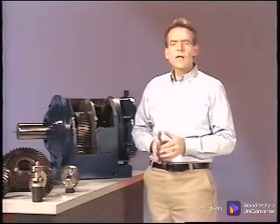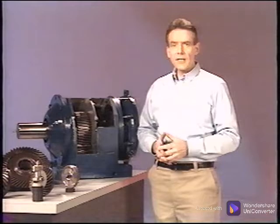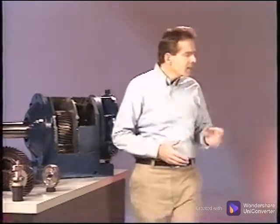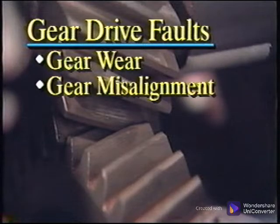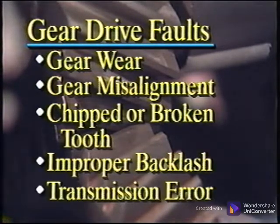In the previous section, we pointed out how gear mesh is generated and how it is directly related to the number of teeth on the gear and the speed of the shaft. Here, we will consider the effects of load on a gear set and examine some specific faults and how they show up in spectral and waveform data. The faults we will consider here are gear wear, gear misalignment, chipped or broken tooth, improper backlash, and transmission error.